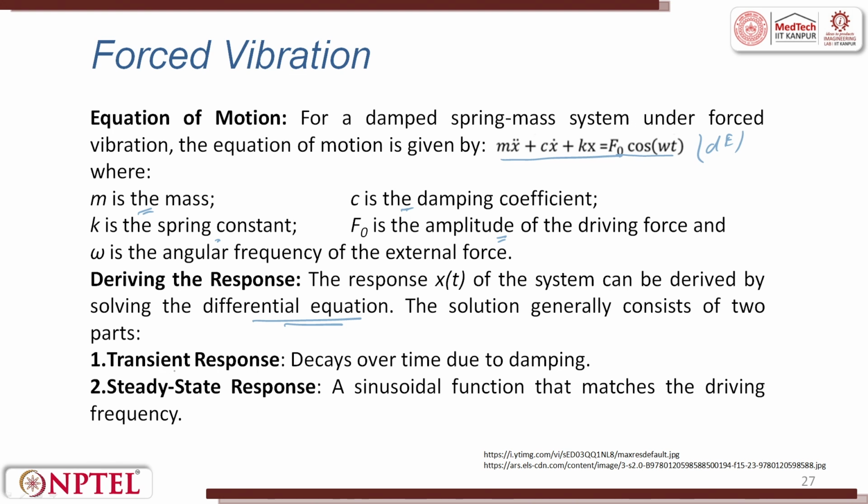The differential equation will give two parts: the transient response, which describes decay over time due to damping, and the steady state response, a sinusoidal function that matches the driving frequency. We will get both these values in this forced vibration.